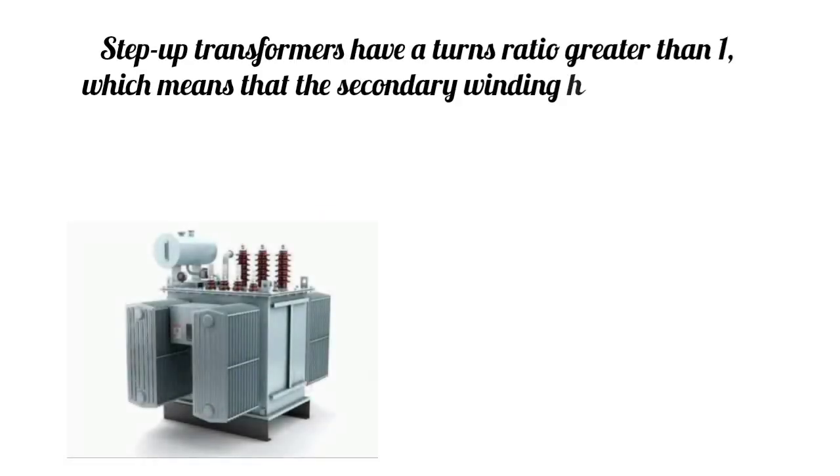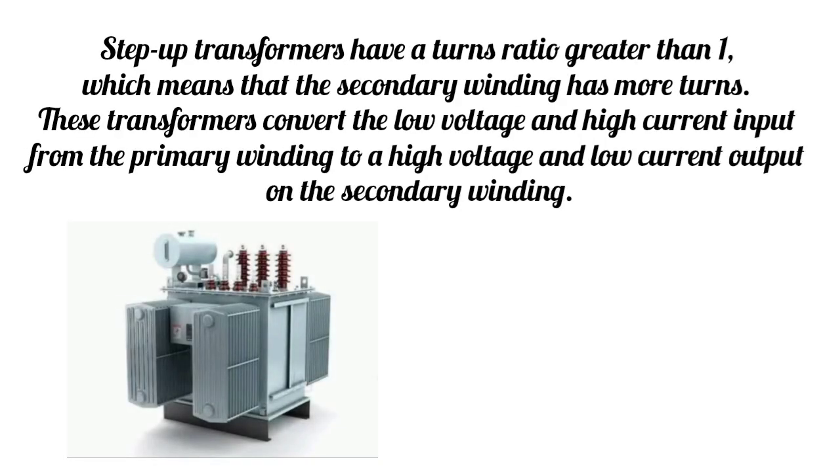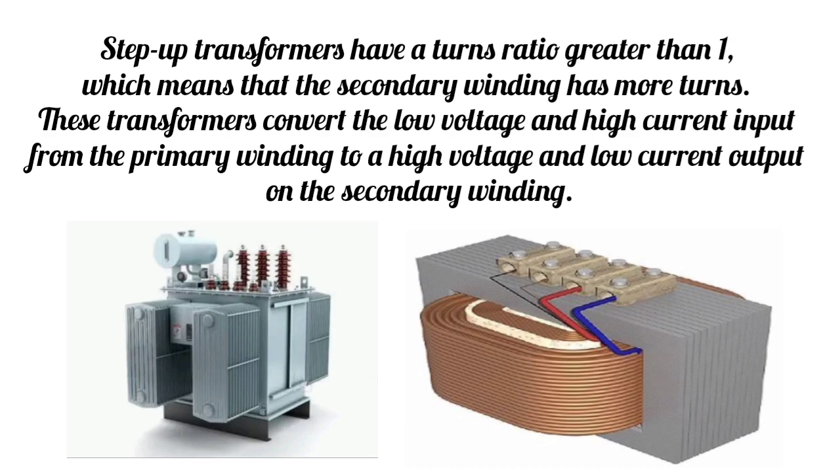Step-up transformers. Step-up transformers have a turns ratio greater than 1, which means that the secondary winding has more turns. These transformers convert the low voltage and high current input from the primary winding to a high voltage and low current output on the secondary winding.